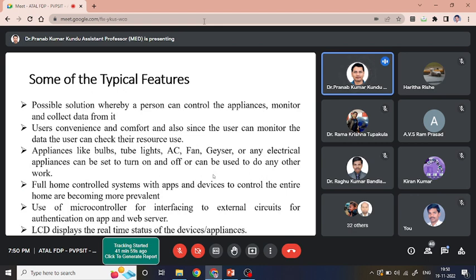I know the physical issues are there, obviously. At the same time, you have to keep in mind that the blasting of the cells can be prevented by using some sensors. If the sensors are put appropriately at each cell, and the temperature of a particular cell suddenly exceeds the value, it will be indicated in your system.